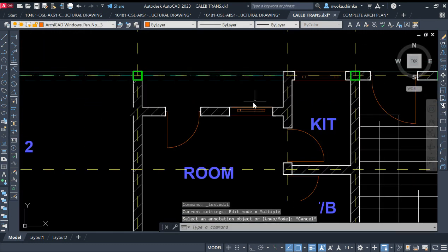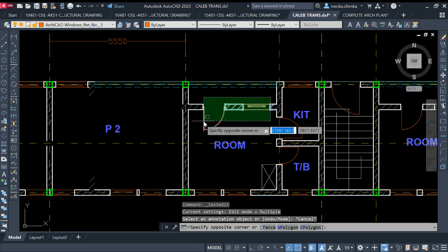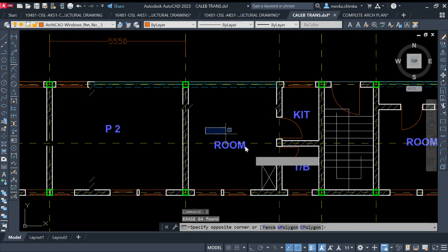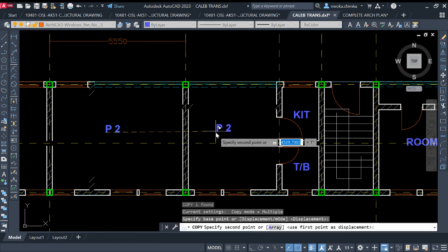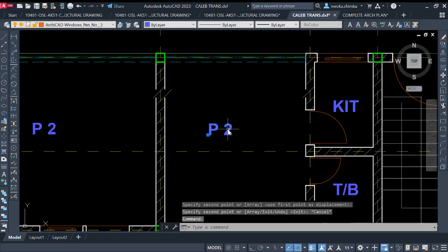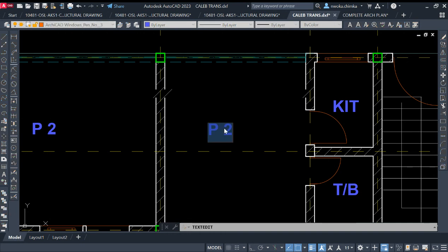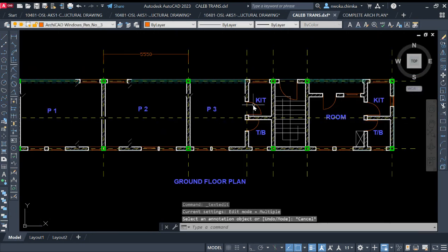And then right now, I'll go here again, remove this place, and call here panel 3 to form a panel here. I don't want all this. You can see how we are doing what they call structural framing right now. Structural framing, this is what they call GA drawing, which is called general arrangement drawing. So this is now panel 3.